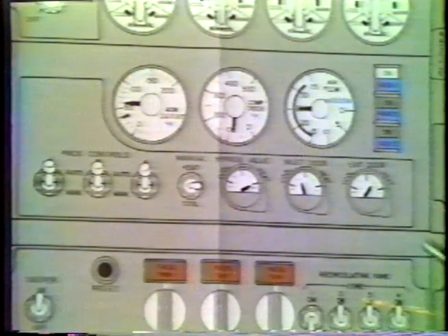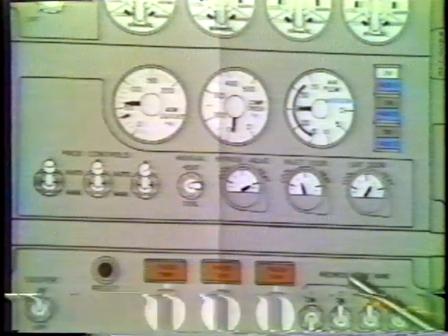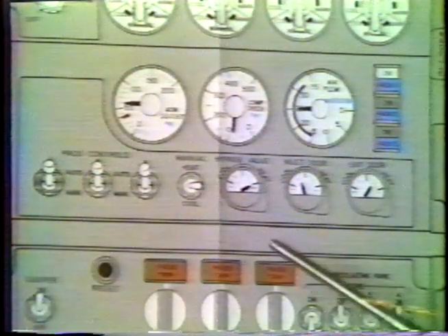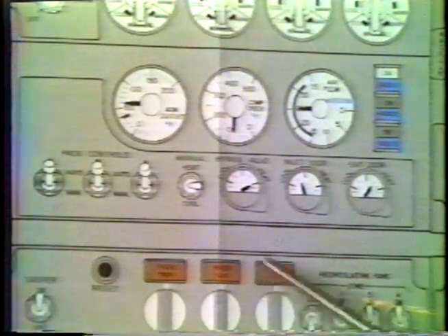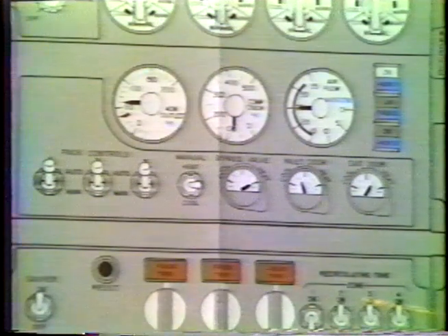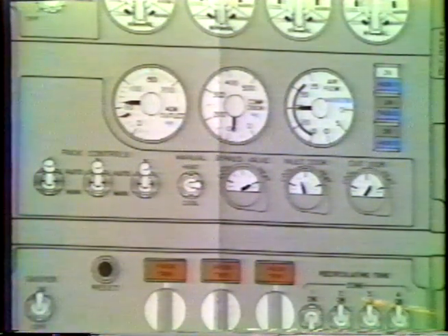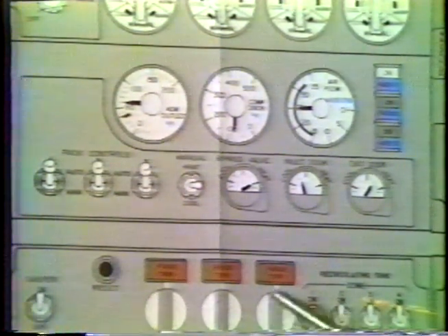I might bring out the point that since you don't really need 3 packs, if you're having trouble with a pack, it might be better to operate with a pack inoperative and just operate on the remaining packs than to try to make a pack that isn't working right do the job.